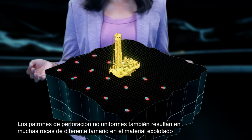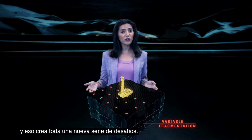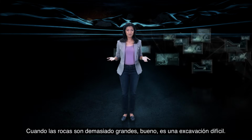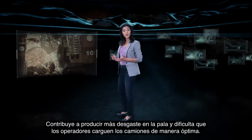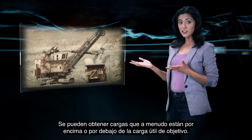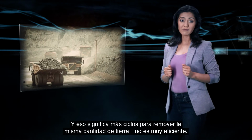Inconsistent drill patterns also result in a lot of differently sized rock in the blasted material, and that creates a whole new set of challenges. When rocks are too big, well, it's tough digging. It puts a lot of extra wear on the shovel. And it makes it difficult for operators to optimally load trucks. You can get loads that are often over the targeted payload or under it. And that means more cycles to remove the same amount of dirt.